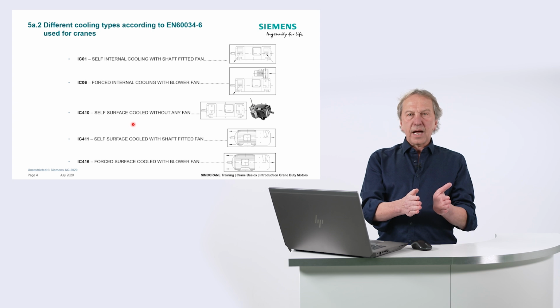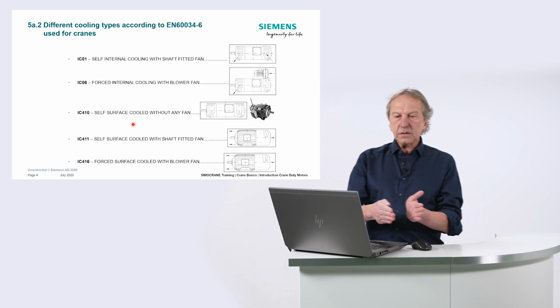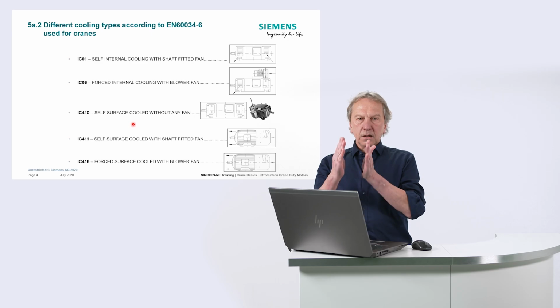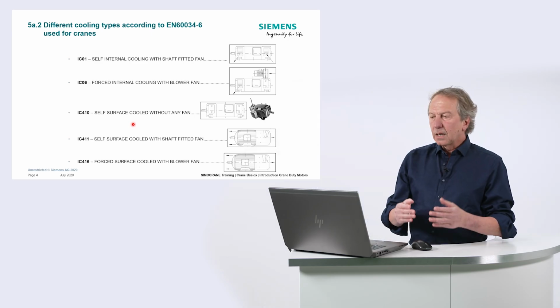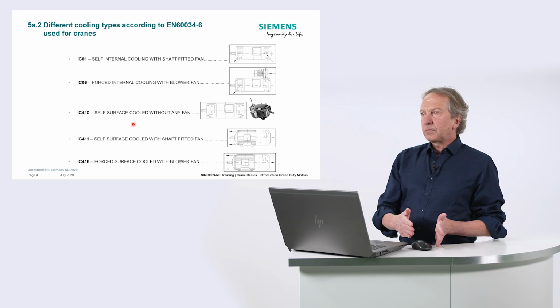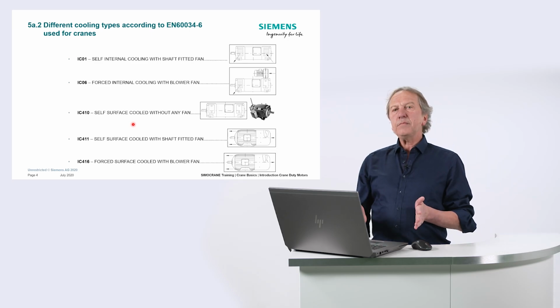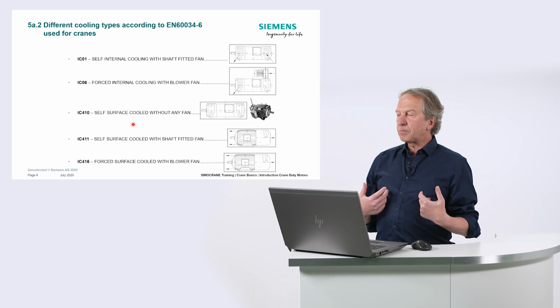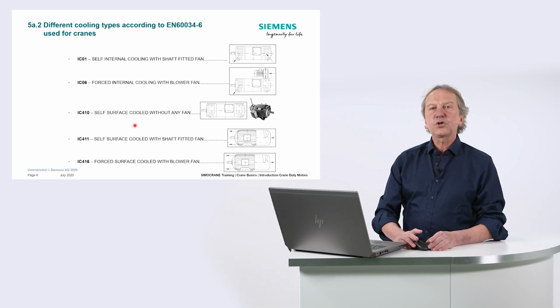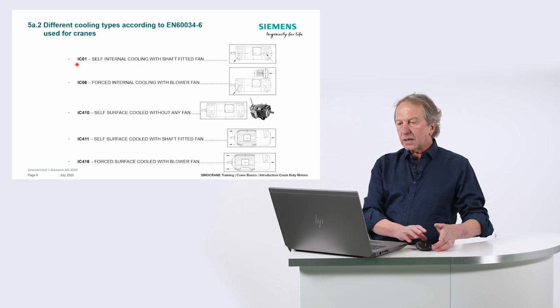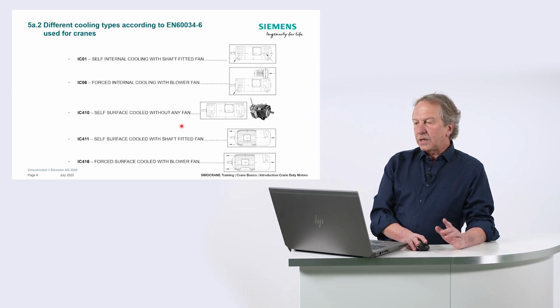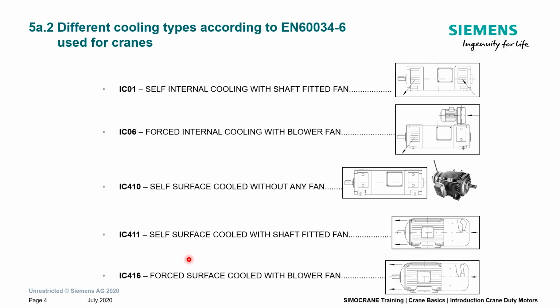And after a certain time, when this job is finished, he just traveled to the next row of the container compartment, and that means the crane is traveling for a very short time and then comes to a standstill. That means for the motor that the thermal utilization is not very tough, and that's why whenever it's possible we use these gantry or trolley motors without any fan. I will explain later on what is the benefit and what is the disadvantage if you install a fan in gantry drives.